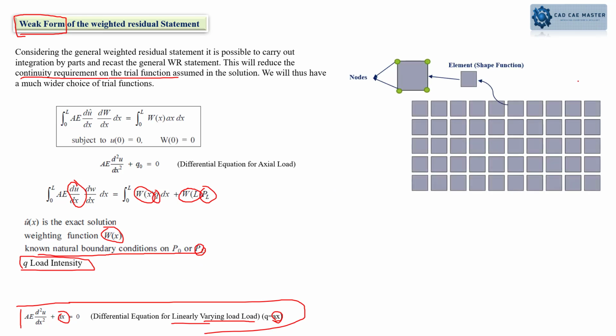Now if we consider the same model we were working on, I take an element with a shape function, and these are the nodes, the quad element, so here these are the 4 nodes. On these nodes we try to simplify. If I consider u hat of x, y and try to explain this particular scenario, it might confuse you, so we simplify this equation into ui, covering all the nodes 1, 2, 3, 4.